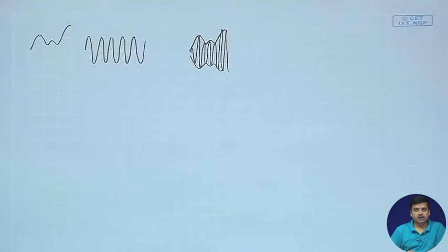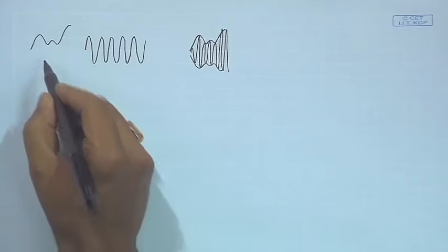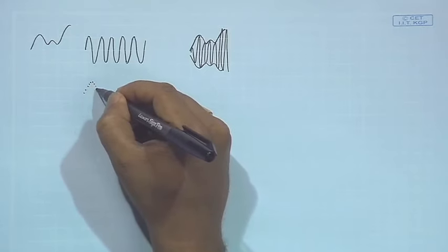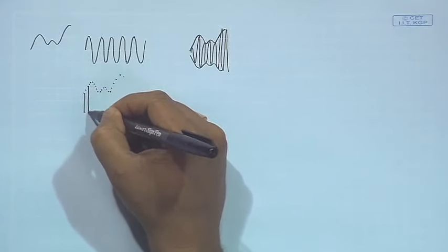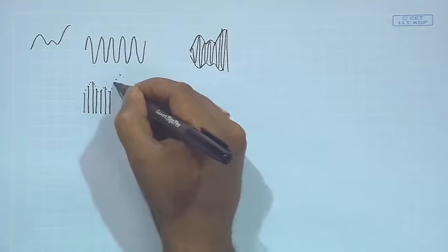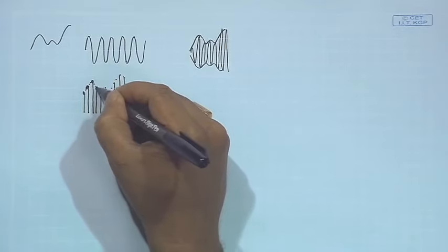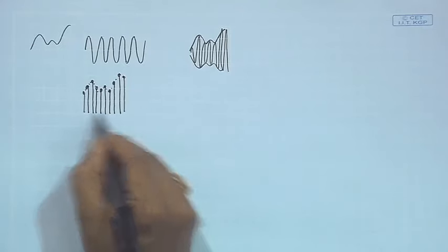Whereas, if we are talking about a digital communication system, the first step that we generally do is to sample the source. So, when you are sampling the source, let us take for example this particular waveform as the source signal, and due to sampling we are going to get, let us say, samples. We will be sampling at a rate which is more than twice the maximum frequency content. So, let us imagine that these are the samples, right, and then these pass through a quantizer.